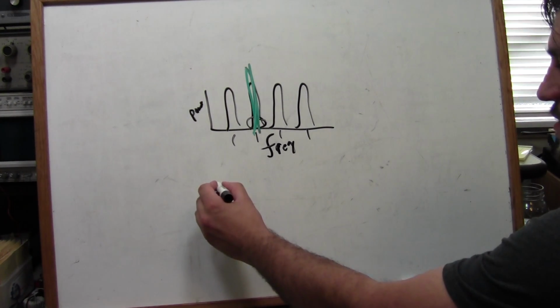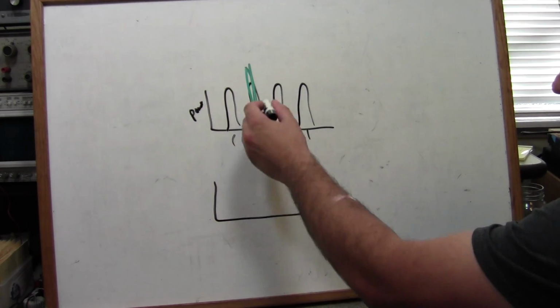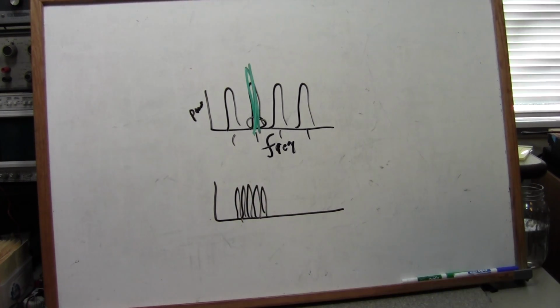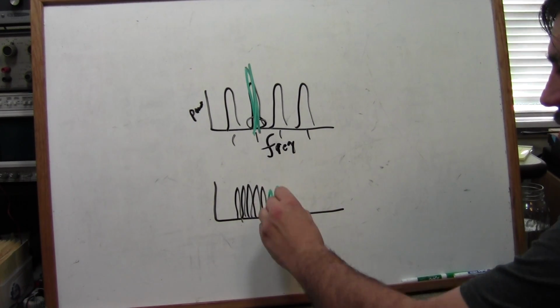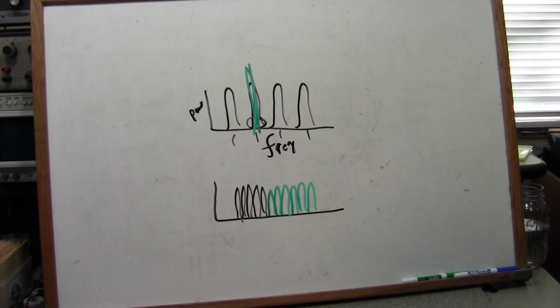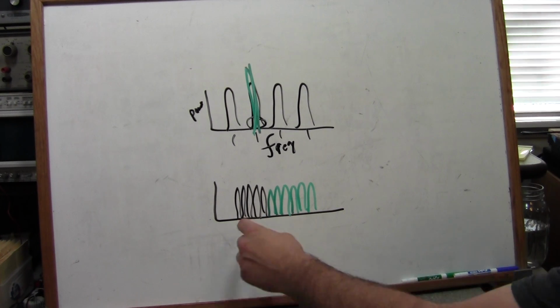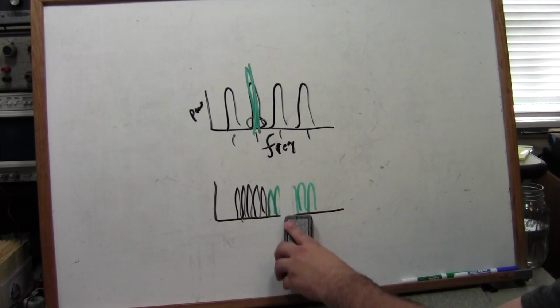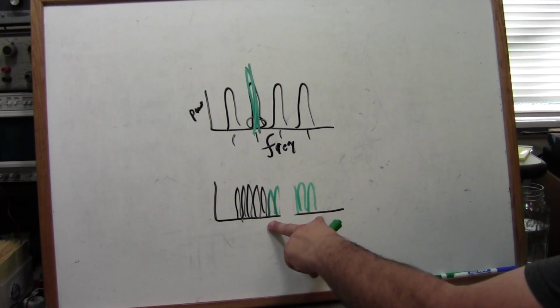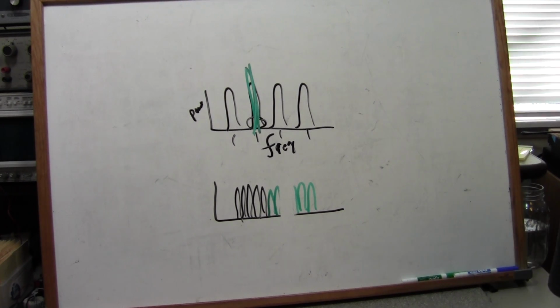Orthogonal frequency division multiplex instead takes what would normally be one large carrier and spreads it over a number of smaller carriers, like so. Then another station can come in like this. This is hugely integral to LTE and most modern high bandwidth cell phone networks, in addition to a multitude of other modulation systems. The advantage here is that now if you suddenly have selective fading at one specific frequency, the station still has other useful channels with which it can still convey the information.